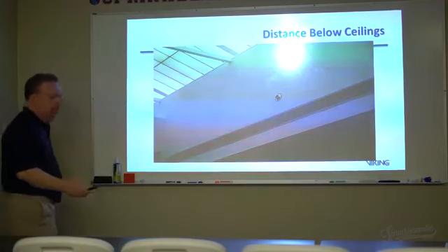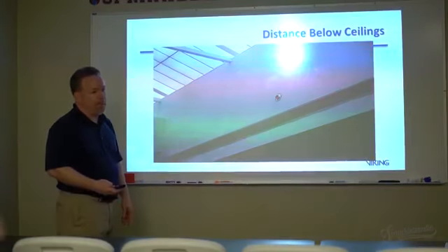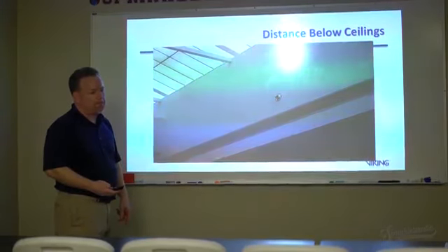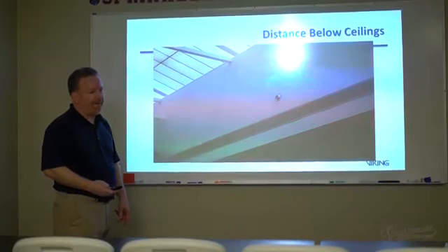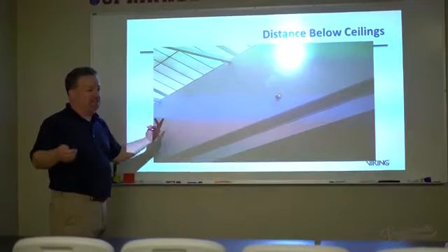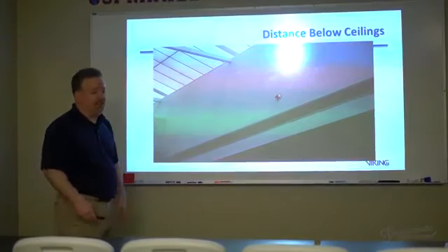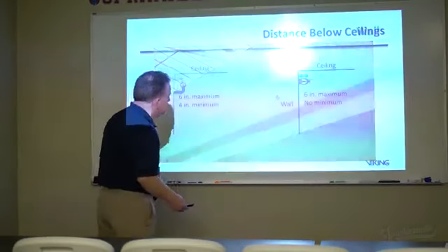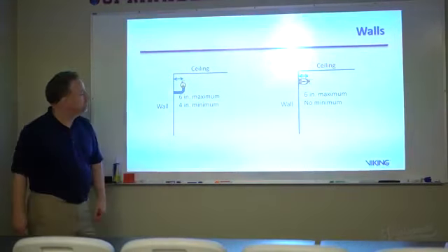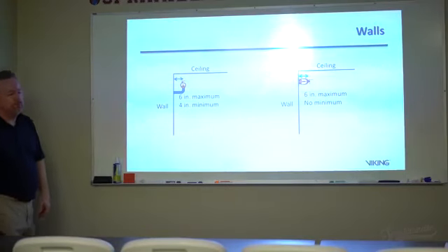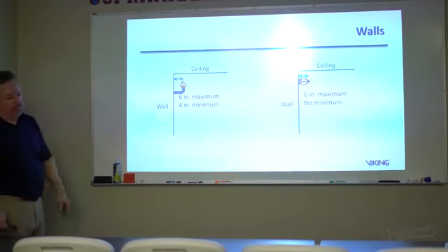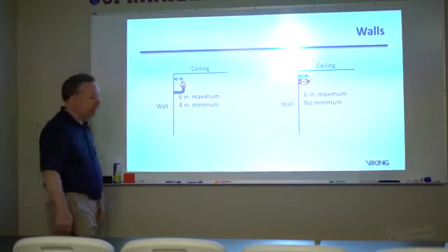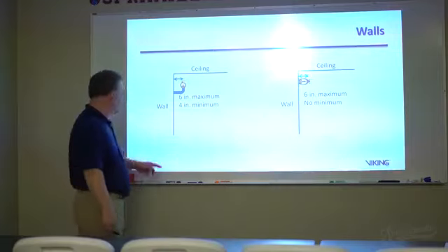We have a building that has an atrium. It has a deluge system at the 4th and 6th floor. They have sprinkler heads on a wall like that, but they're open deluge heads. Well, in that case, the detection's going to send them running. Every month, the guys that clean the carpet in the rooms run it on the second floor, come up and hit the infrared beam. They set that off several times.